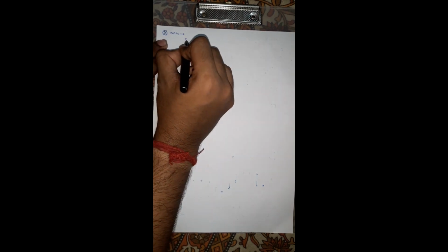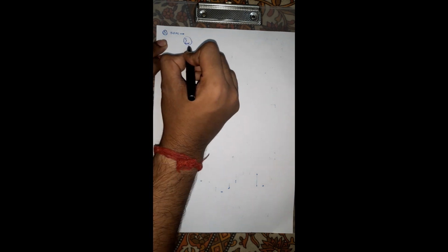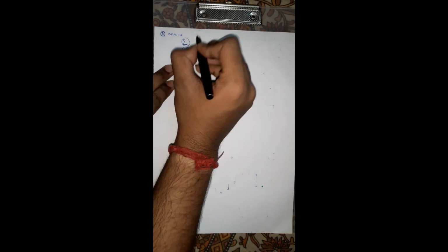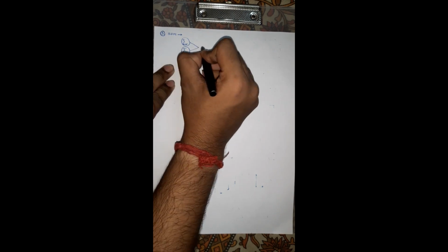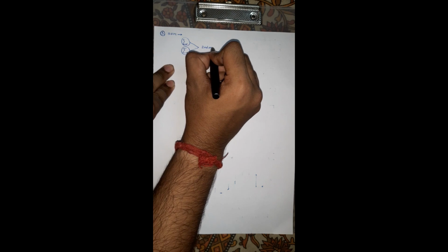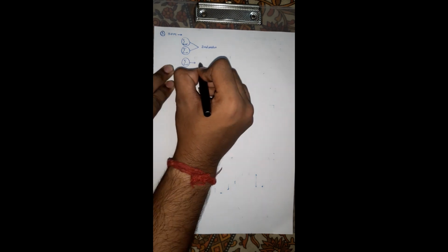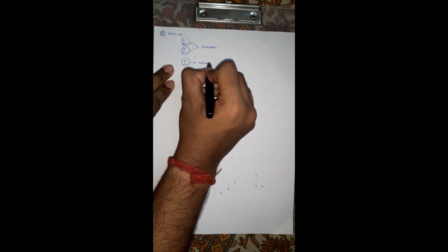But as there is a sigma block over there, that's why it is called a sigma delta modulation. If you find that in the circuit there are 2 sigma blocks, then it will be called a second order sigma delta modulation. And if you find that there is a single sigma block, then it will be called a first order sigma delta modulation. See, the sigma block is nothing but a summation block.